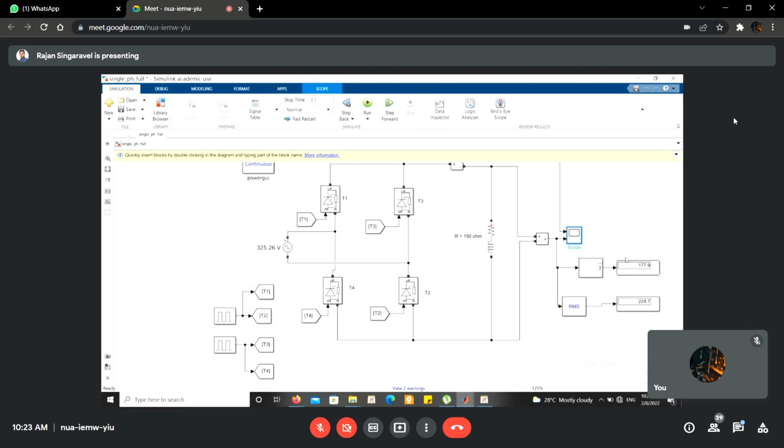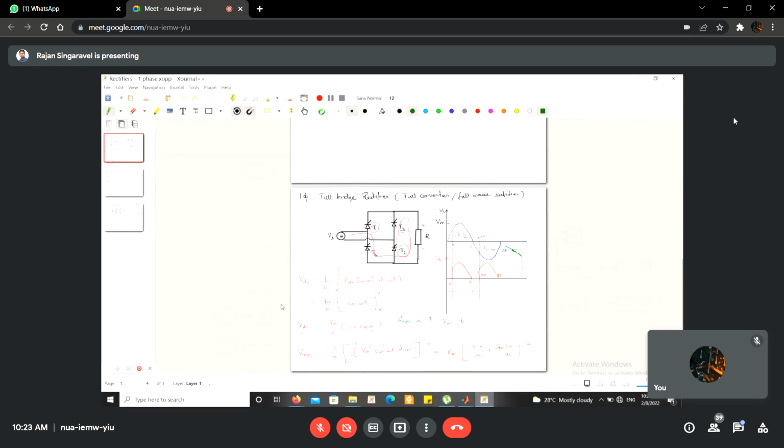So when compared to the resistor, inductance is more dominant. So more negative voltage is appearing. You have lesser average voltage across the loaded terminal, right? So now with this concept, let me give you the equations for this particular full converter.